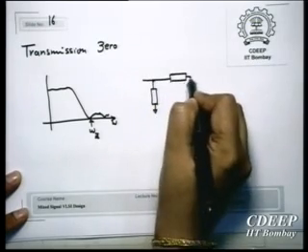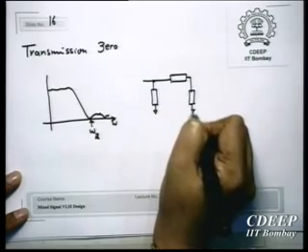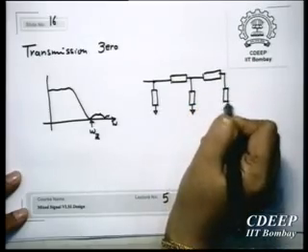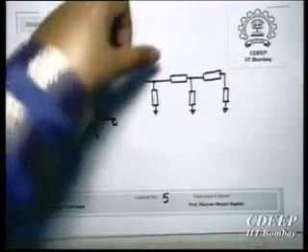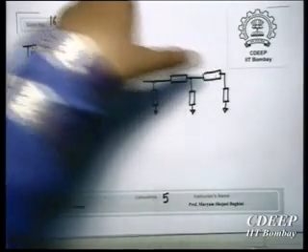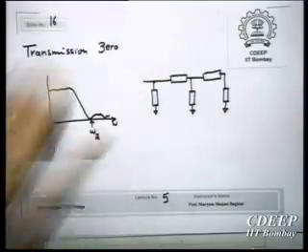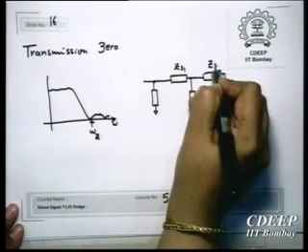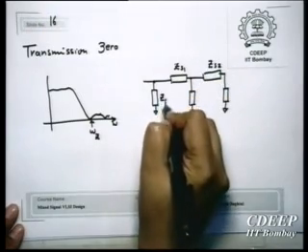In a ladder configuration, components are placed like this. Therefore, if you want to create a zero, it's enough to cut it here, or here, or here. I call this the series impedance, and these are parallel impedances in general.